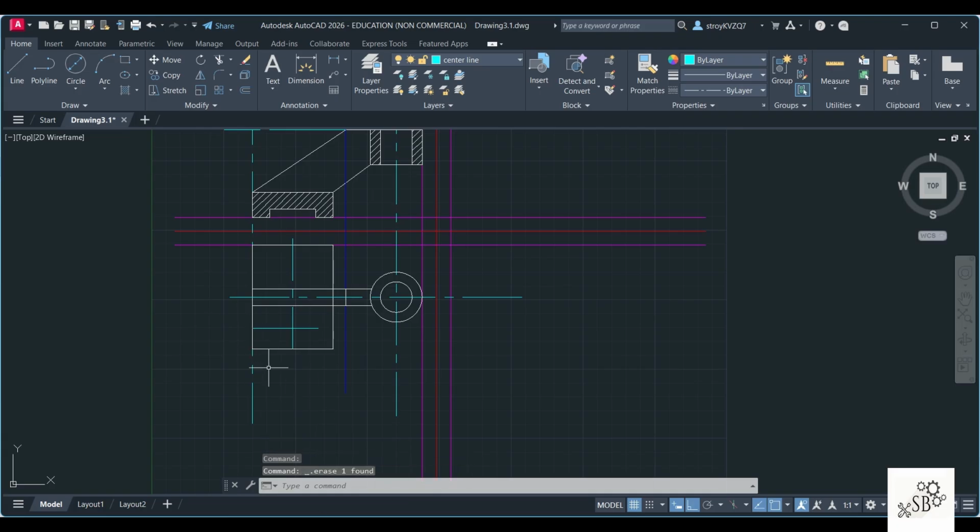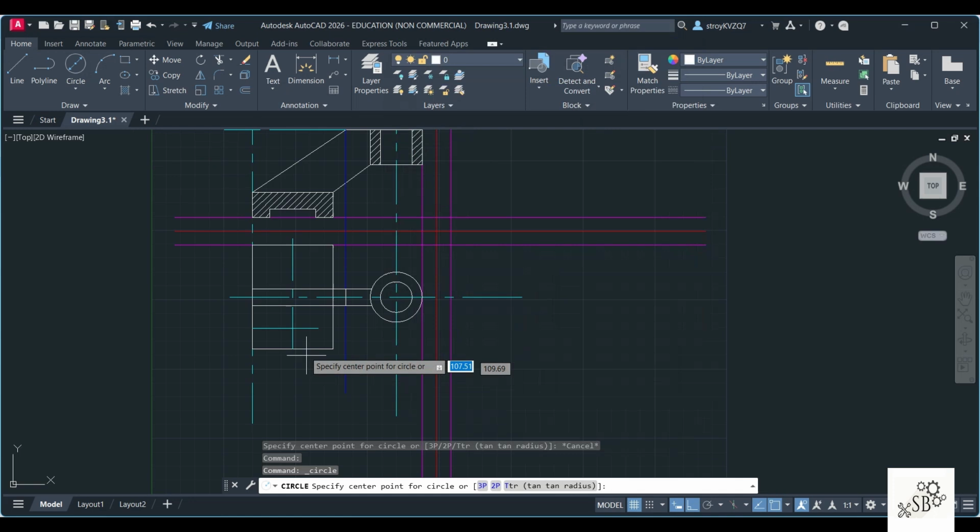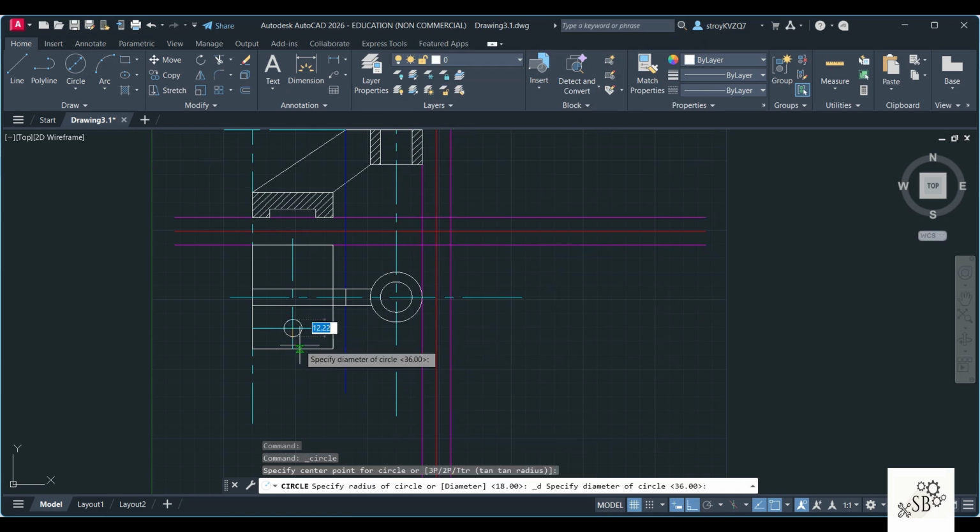This is not required. Then I'll go to zero line, center diameter. Diameter is given as 12. So from here, I'll draw a circle of diameter 12. Now once we have drawn the circle, you can draw also over here. So I will go to mirror option. I'll select this center line and also the circle. I'll press enter. This is the mirror line. Erase source object, no.